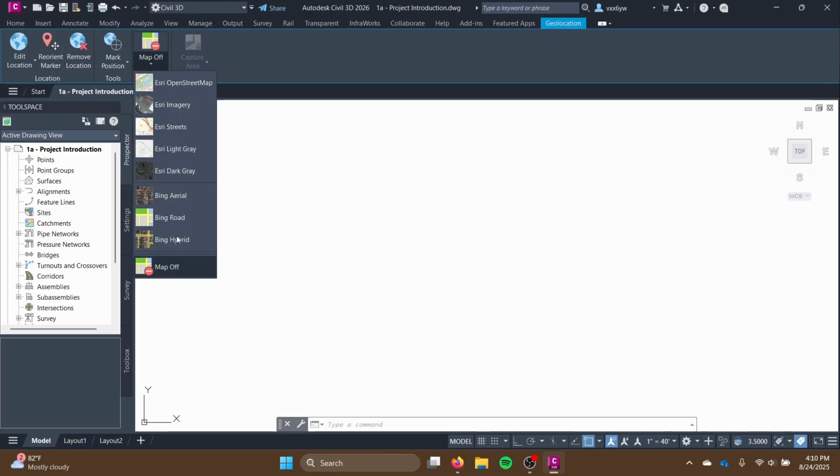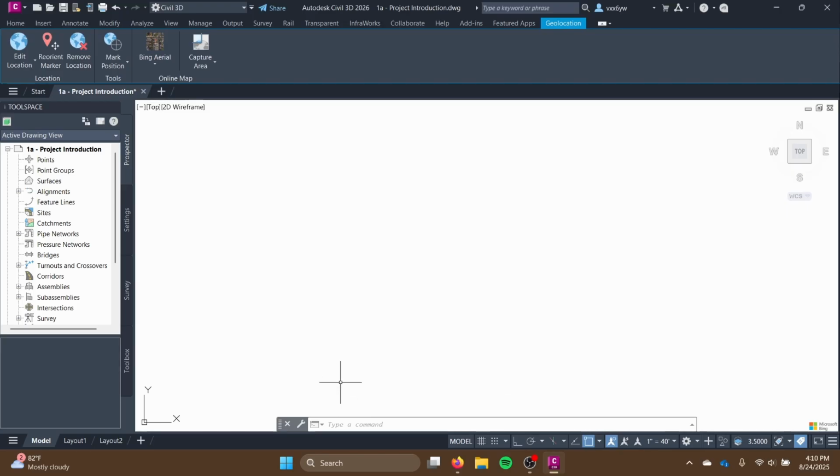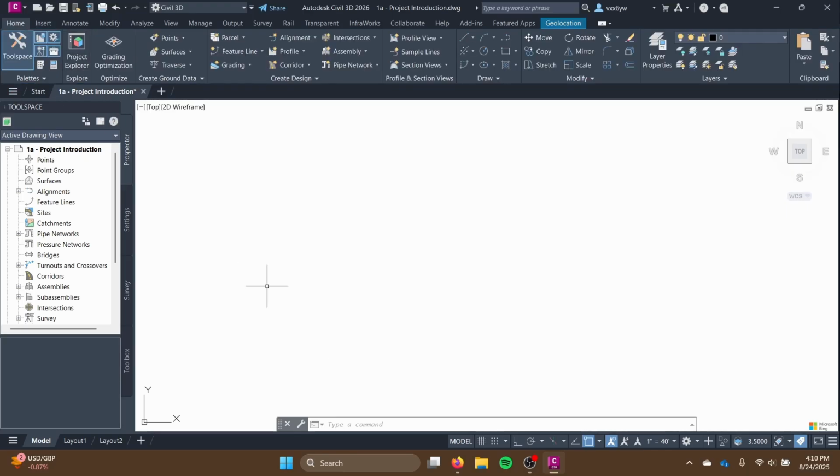You can pick any of these that you want to. I'll start with the Bing aerial view. You can see now that the Bing aerial view is on. Somewhere in this workspace, the entire state plane that we downloaded is in an aerial view. So we need to show you what that looks like, but to show you what that looks like, we need to find a way of finding that place. And a great way of finding that place is inserting geo-referenced coordinates.